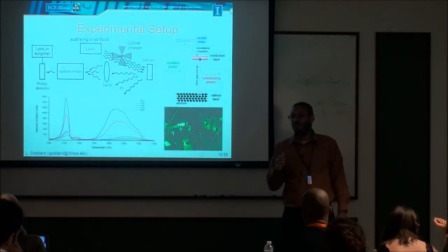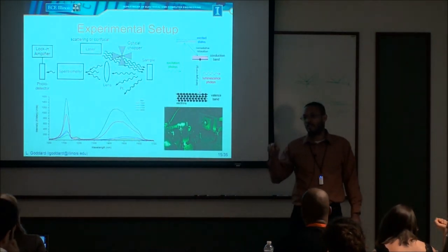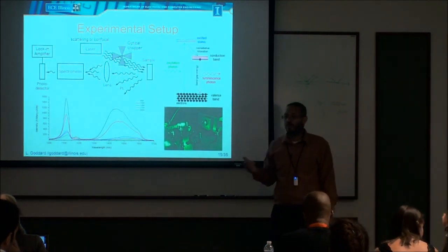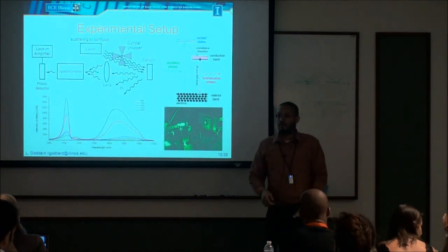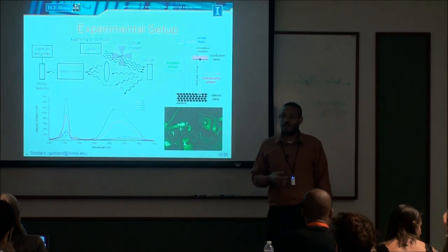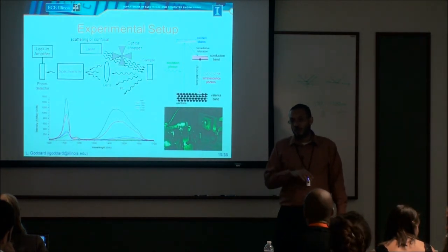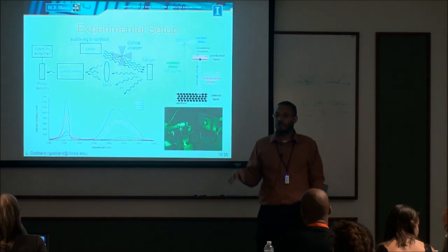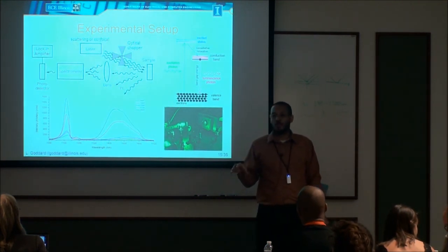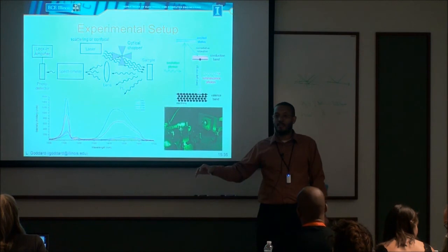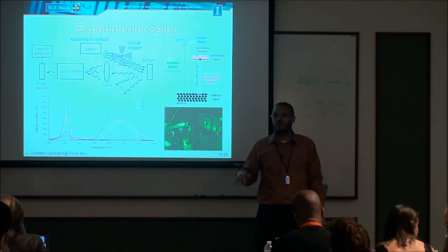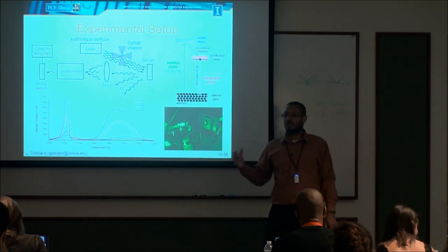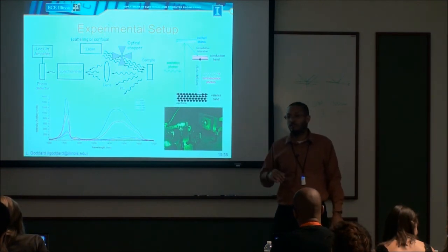But two, the wavelength during the pulse can change. As it heats up, it changes the wavelength. And that may be okay for some applications, but for a lot of things with spectroscopy, it's not a good thing. So the alternative way people do it is they have a CW laser and an electroabsorption modulator. The electroabsorption modulator is outside of the laser cavity, so you can turn that on and off as fast as you want without affecting the performance of the laser. So it's like a chopper, except it's an electrical version of it.